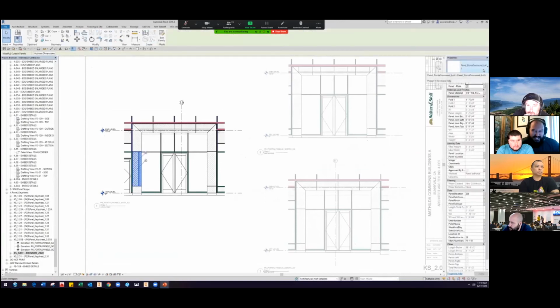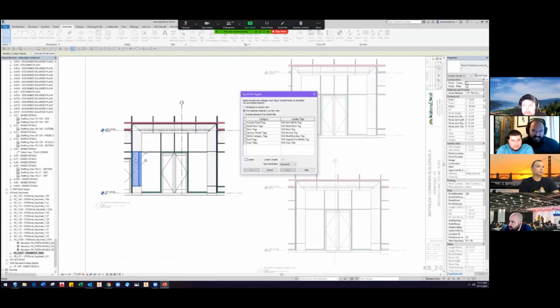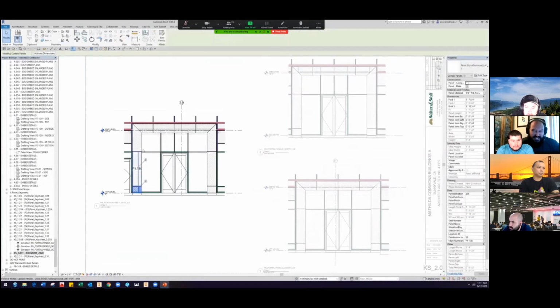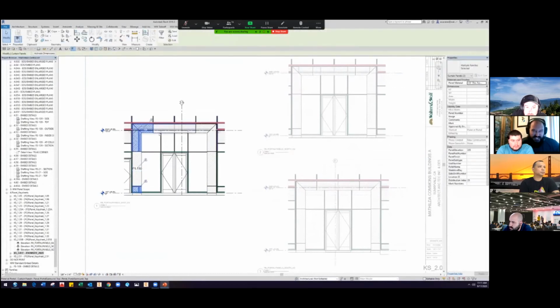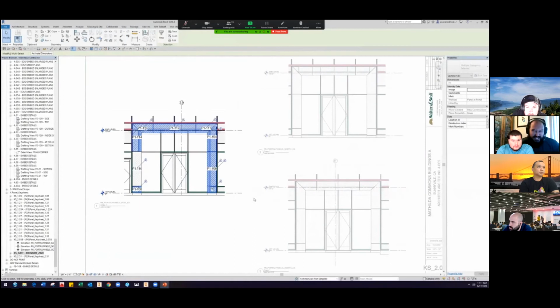So I would highlight a panel, make sure it's the main family, not the child family in the case of this building, which would show a mark number, which we can then go to the tag all, select the multi-category tag, and it will apply, it will show the mark number, and then you just select the panels all around, make sure that you've chosen the main family.